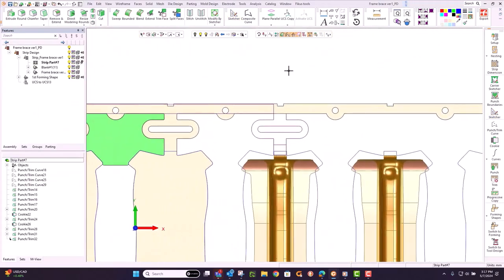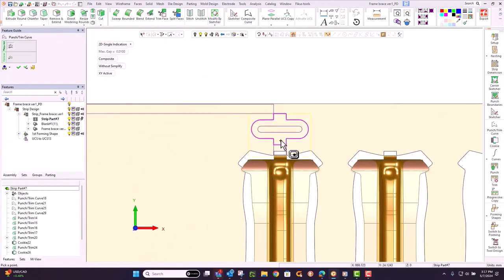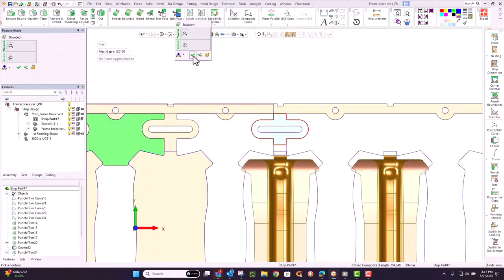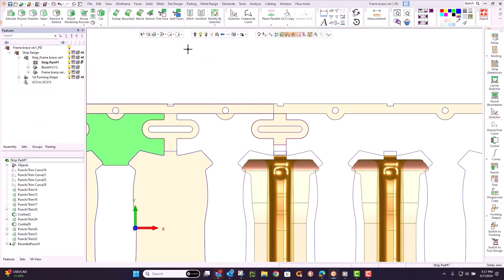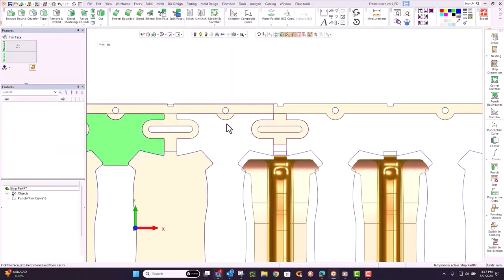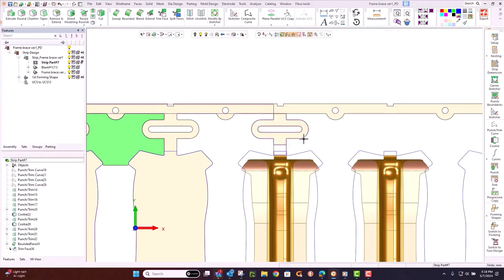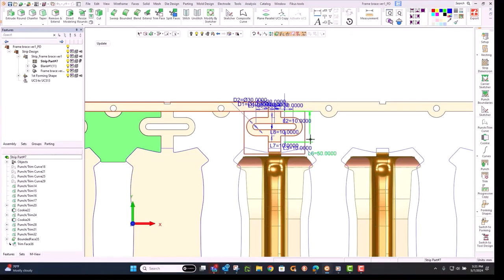We'll put a quick little face in here where we know that expanded web needs to go. And that being said, we can simply adjust it. So I know it's going to expand out to meet the part. We know that distance, we make an adjustment in the sketch, and then we'll see as that expanded carrier transforms into an opened up, expanded web.